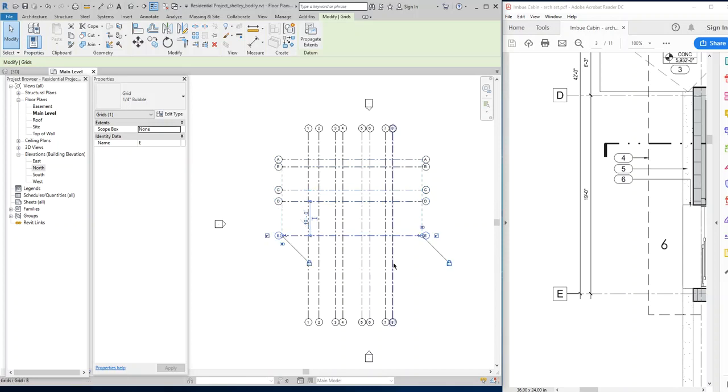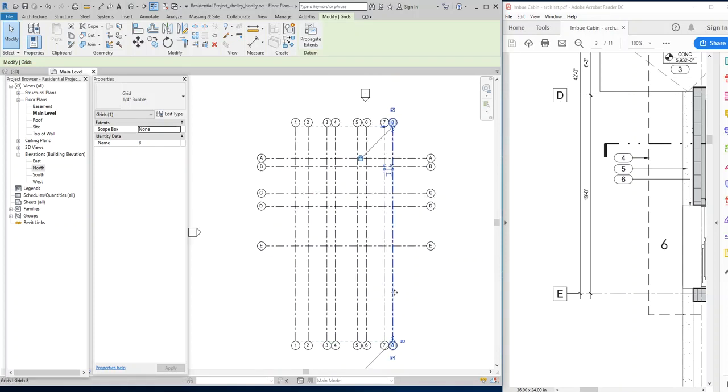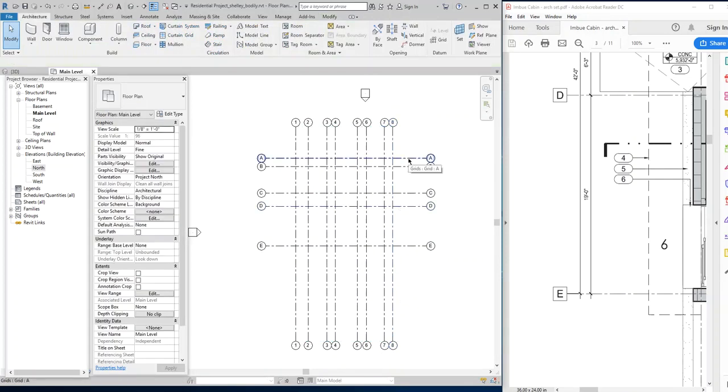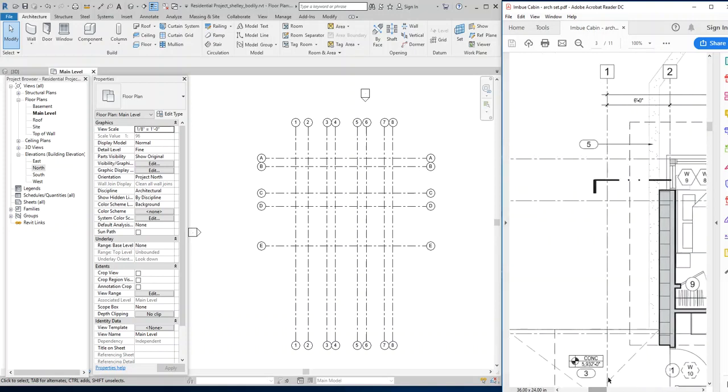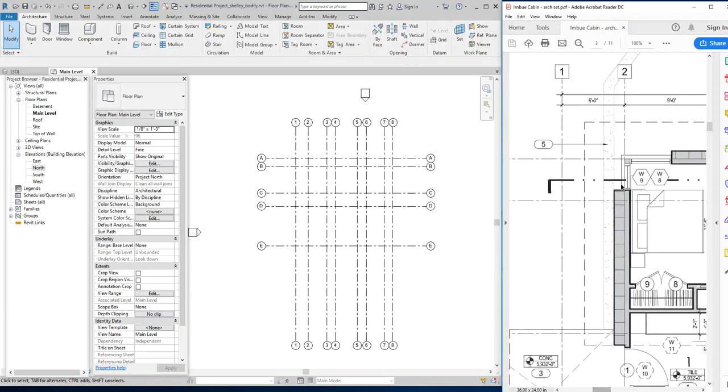This is a little bit long, so I click on this, right? I think I said this before too. In Revit, you were probably thinking, well, why did you choose to put A right there? What dimension is it from the top of this down? Well, I don't have an answer for that, right? I just started creating my grid, A, and it didn't really matter how far it was from this vertical grid here. The only important thing was that at 2 and A, that's where my wall starts, or the window starts right there, I guess I should say. The core of that wall starts. So I didn't pick a specific place to generate this grid.